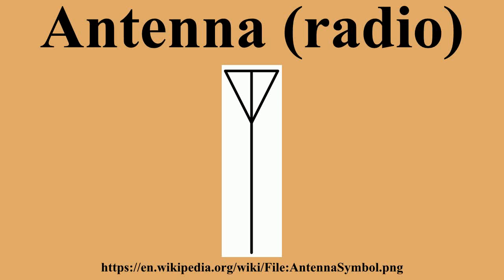In common usage, omnidirectional usually refers to all horizontal directions, typically with reduced performance in the direction of the sky or of the ground. A directional antenna usually is intended to maximize its coupling to the electromagnetic field in the direction of the other station, or sometimes to cover a particular sector such as a 120 degrees horizontal fan pattern in the case of a panel antenna at a cell site.